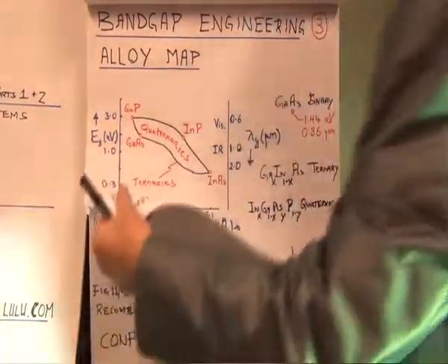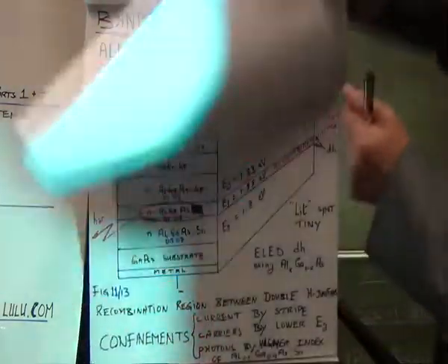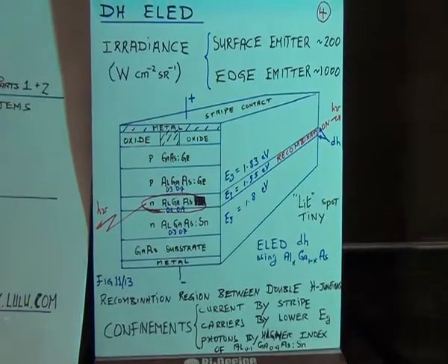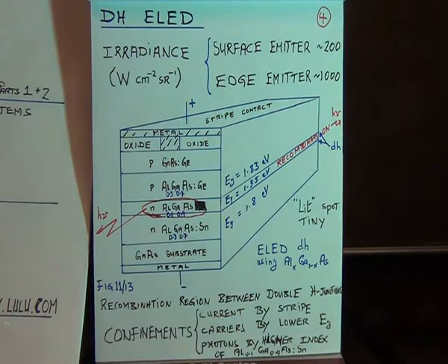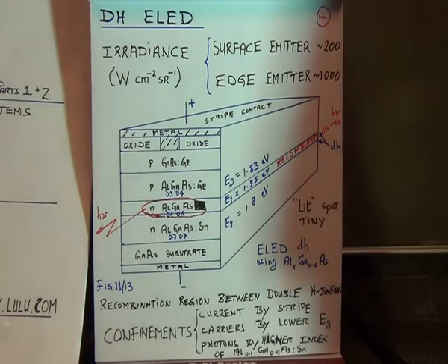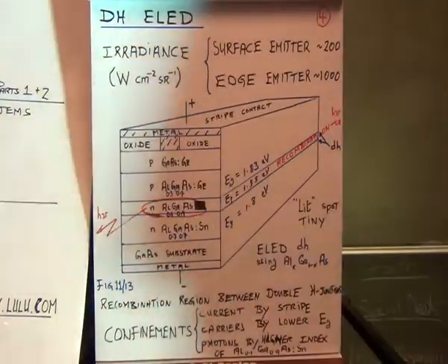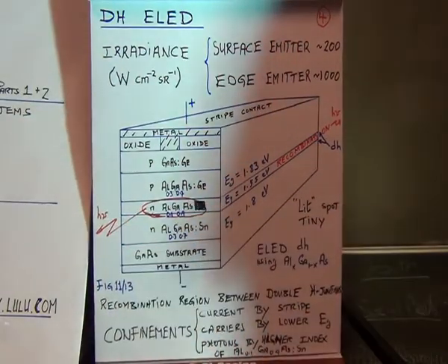Before we do that, we can make an immediate improvement to the LED. The next improvement which occurred was the edge-emitting LED, illustrated here. There's a lot more processing involved when you're growing your wafer. You take a wafer that you'd grown some other day, cooked elsewhere, and you'd start off with a wafer of just gallium arsenide.